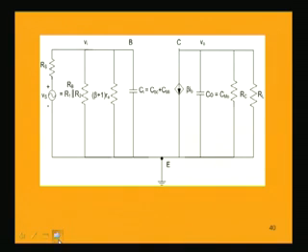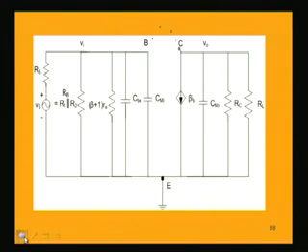Now we can replace these values and find out CMI and CMO. We will have in the amplifier figure two capacitances in the input side, because CMI is there, CBE is already there, and in the output side of course there is one capacitance. Now we can combine these two parallel capacitors, because parallel capacitances give the equivalent just by summing up.